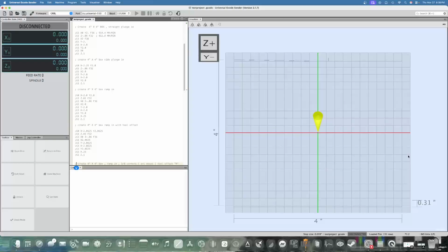So this is where tool offsets come from. And again, if you're a programmer, no, GRBL does not use G40 or any type of tool size compensation at all. So everything has to be calculated into the G-code. And in this example, you see it's a 1/8 inch, so half of that would be a 1/16. I hate that little dot thing that comes up on here. Probably a setting in there to turn that off.